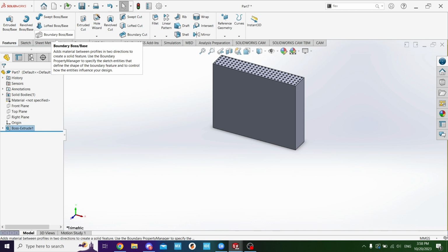I don't know if you guys have gotten to the point in which you kill your computer with SolidWorks. So just be careful. That way is a better way overall. If you do this in 2 steps, it will become a problem when you're in RoboMaster and you have upwards of 500 part assemblies and assemblies of assemblies. I've done that already. The chassis is like 300 already. You guys get that, right?